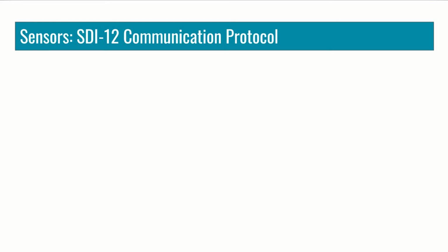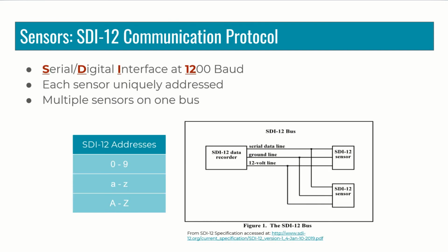As indicated, each sensor does not have to be connected directly to the node. How can that be? All of the sensors communicate using SDI-12 protocol. With this protocol, each sensor is given a unique address that functions like a phone number. Each sensor can be queried individually without causing confusion about where the information came from. This means that the sensors can be connected to a single cable going to the node as shown in the figure. Now we'll describe the three types of sensors, starting with the soil water sensor.